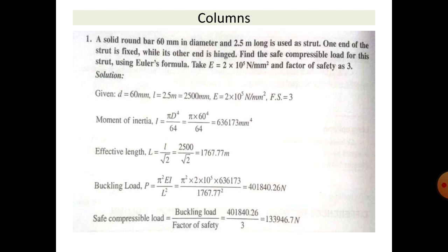Whatever we calculate through Euler's formula will be the maximum load that can be applied over the column. The load we calculate will be the maximum load that the column or the strut of 2.5 meter length and 60 mm diameter will take.